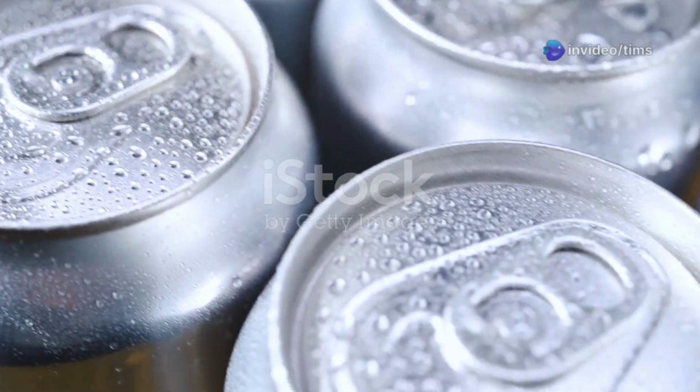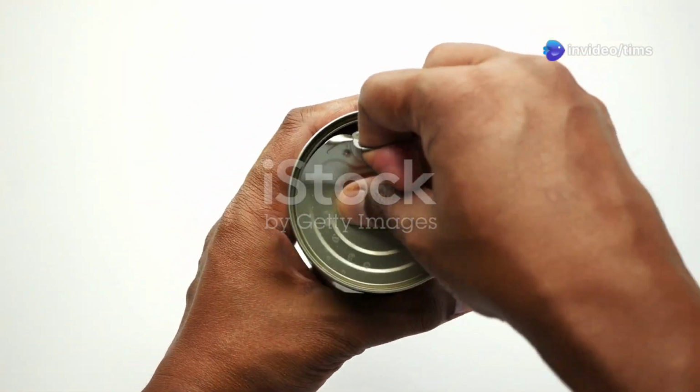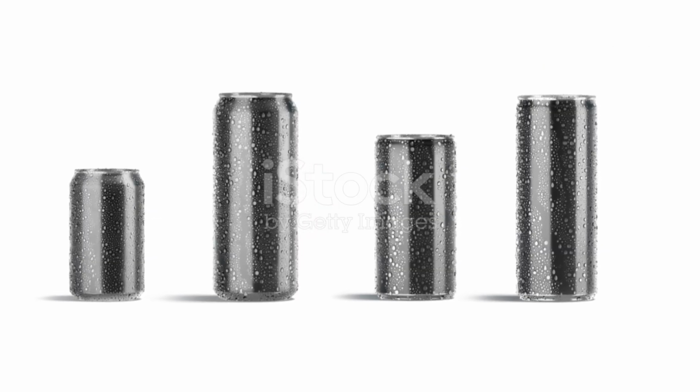Curl defects are imperfections in the can end's curl. These defects can compromise the can's seal, leading to leaks and spoilage. Common curl defects include short curls, long curls, and wavy curls.